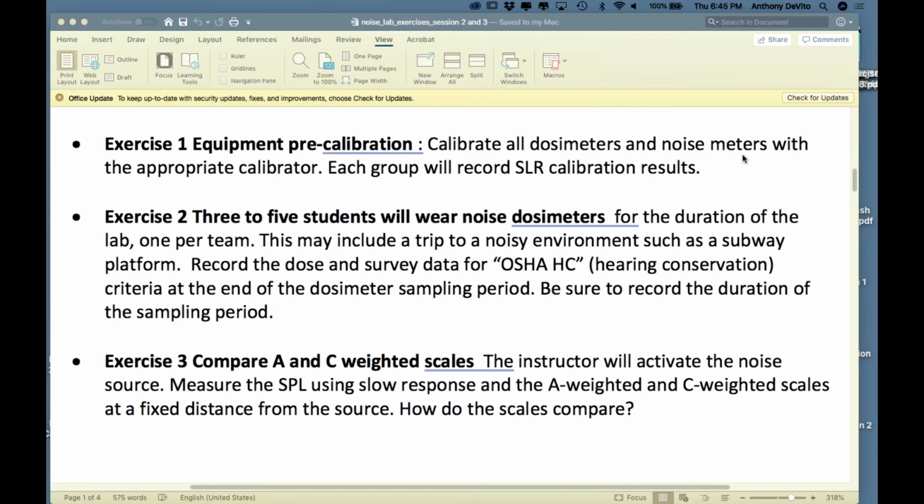Technically, there is another way to calibrate. Legally, sometimes you might have to have 2-point calibration of 2 devices like that. If you are a certified industrial hygienist, you get involved in a lot of legal work, and you wind up on the stand testifying about measurements that you made. I guarantee you opposing counsel is going to say, well, how did you calibrate the instrument? What kind of calibration techniques did you use? What does the manufacturer recommend for calibration? When was the last time it was sent to the manufacturer? These things are supposed to go back to the manufacturer once a year for servicing and manufacturer calibration, and so on and so forth.